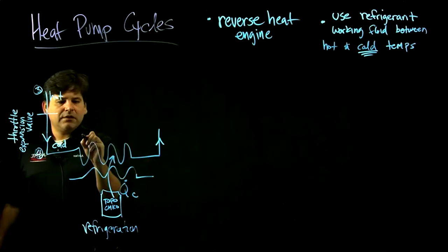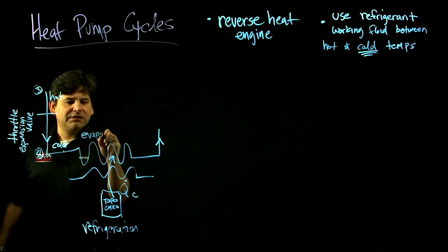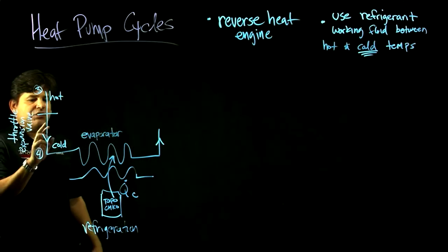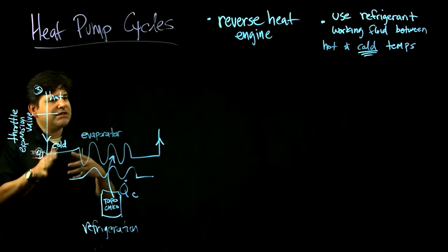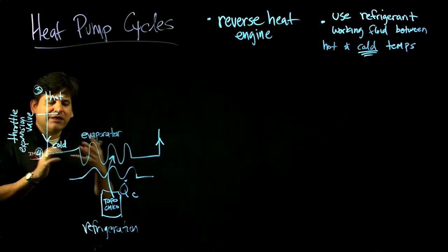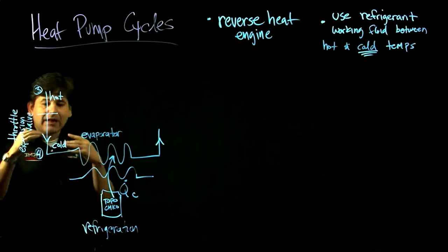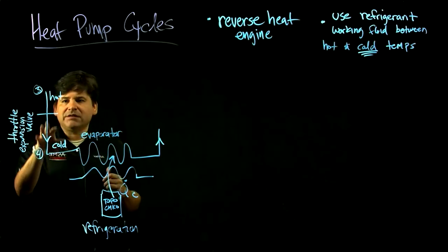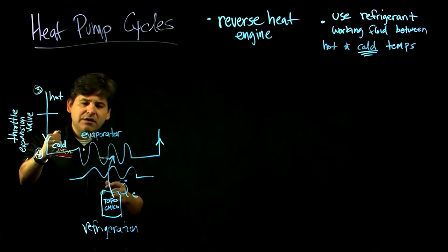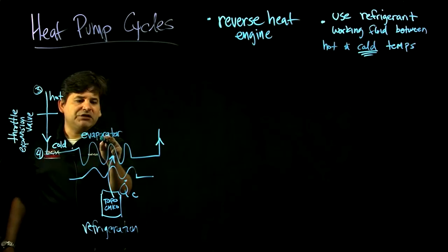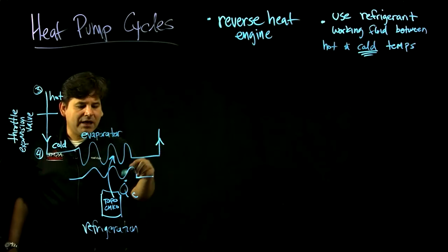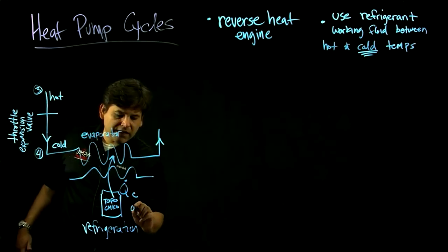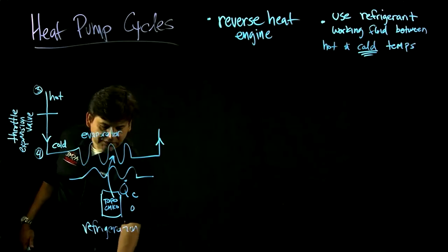So this would be called the evaporator, because as we'll look on the phase diagram, when this refrigerant expands to cold temperature, it falls in this saturated mixture regime where there's both gas phase and liquid phase at cold temperatures. And the way that this cycle is designed is that after it expands at a given pressure to a lower pressure, it's going to complete the vaporization to all gas phase by boiling at, for a fridge, let's say we like our Topo Chicos at like 2 degrees Celsius.